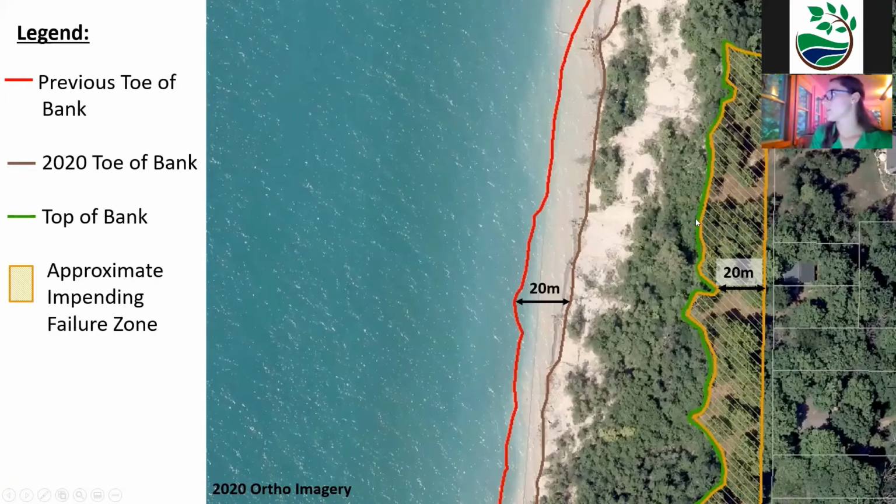And then the green line is the top of bank, and the dashed yellow line is the approximate impending failure zone. So the area that we expect will eventually, or we know will fail eventually. So in this case, about 20 meters has been lost from the bottom of the bluff. And when you project that onto the top of bank, we would expect all of this area to fail eventually.